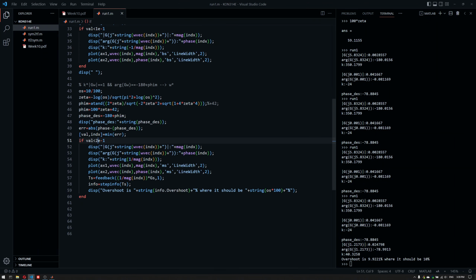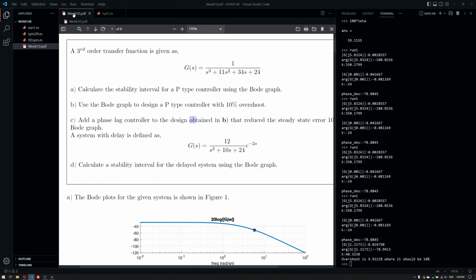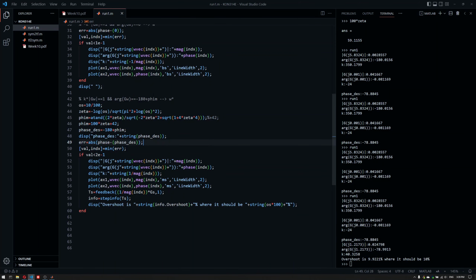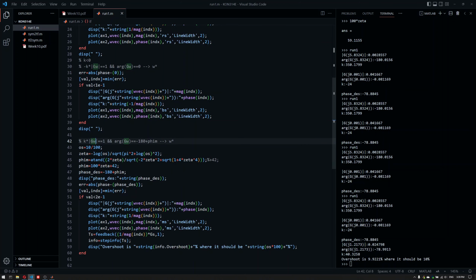And the phase lag design is actually quite algorithmic, I'd say. And the reason for that is the following. You have some steps to carry out, and that's basically it. It's for most of the Bode plot or Bode methods here. You can see that there's a certain algorithm. Search for this, get the frequency. At that frequency, read the gain value. Take the inverse. Take the inverse with a negative sign.